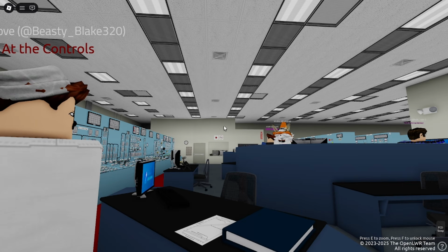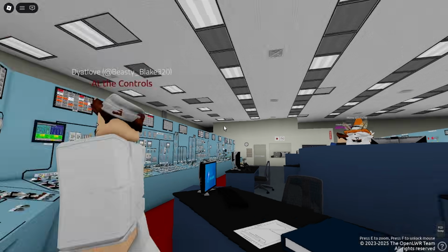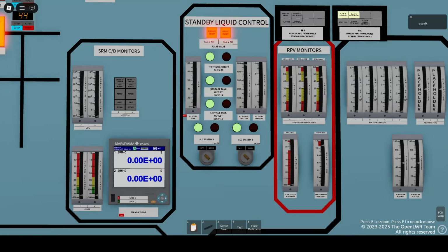Okay, so I understand that's a mode switch in shutdown. APRMs are inoperable. We have level of -50 up slow. We have a pressure of 1096 up slow. We have entries on reactor scram required and power inop. We have low level and high pressure. That is correct. All rods are not in.